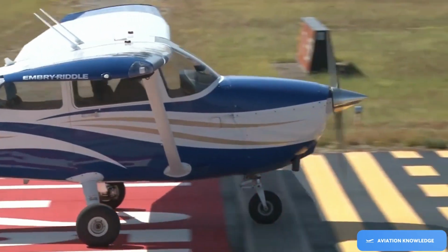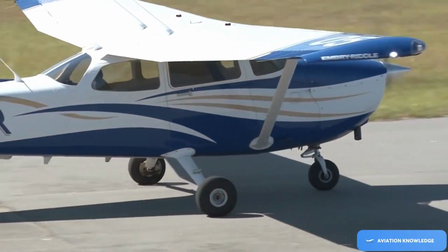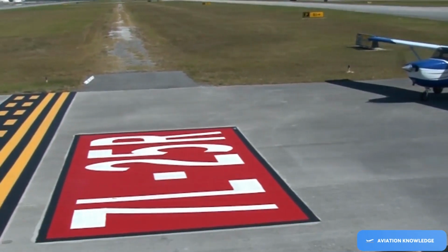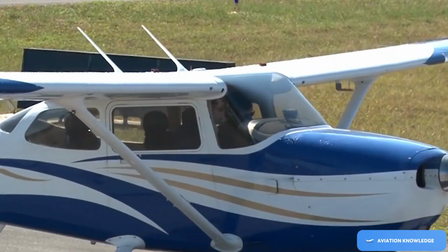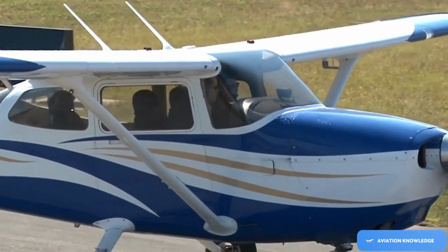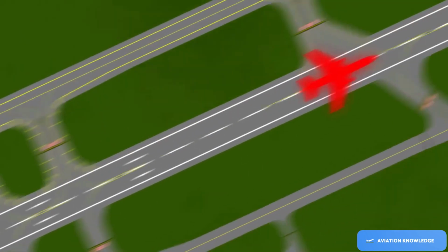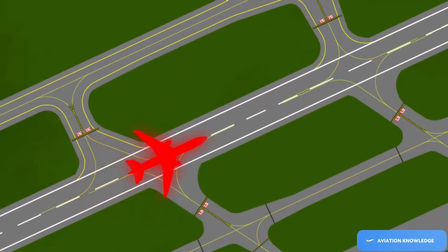The takeoff procedure begins with safely entering the runway. Before ever crossing the hold short marking for the runway, the pilot needs to always visually scan the entire runway length, as well as the arrival and the departure paths, to ensure no hazards like other aircraft or vehicles exist.